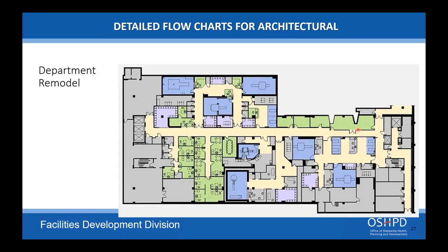They have a single toilet, only a single hand washing fixture in the toilet area, but not in the patient room. They're completely out of compliance, no accessibility, but the rest of this floor is being demoed and rebuilt around those 5 rooms. Okay, everything new going in must meet current code. Those 5 rooms can remain as is with no further upgrades.